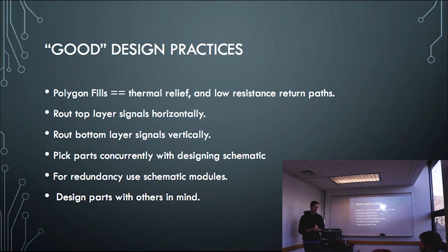Your question was, when do you jump? Yeah, obviously you don't want too many discontinuities in your ground plane for high-speed designs, but some are okay. But you use software to simulate signal integrity? Yes. If we have any doubts, I can get you guys the software, and essentially you can just simulate.